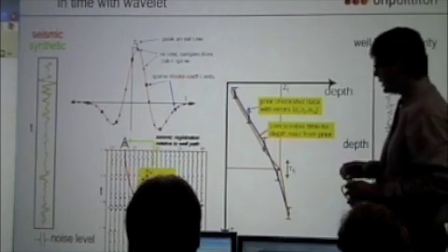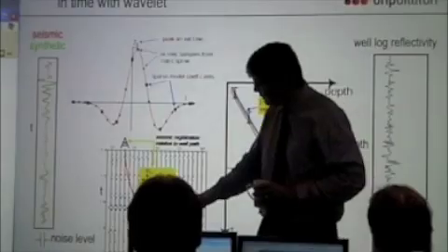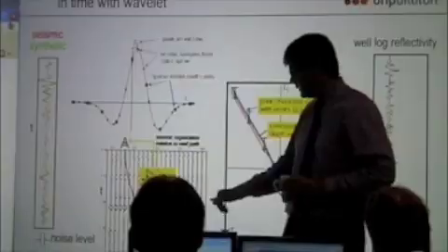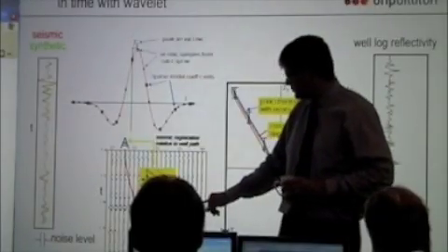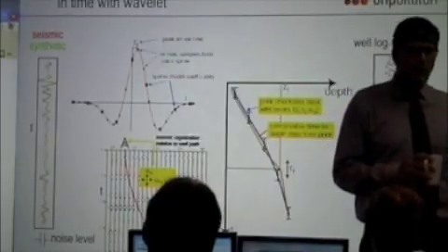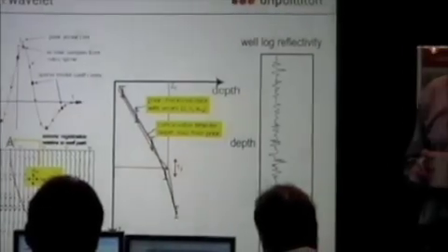Now it gets a little more complicated than that, because a lot of times you'll have very good seismic reflectors. You will be a bit surprised, but many times a good seismic reflector you can isolate and know where it comes in to within about 2/10 of a millisecond.